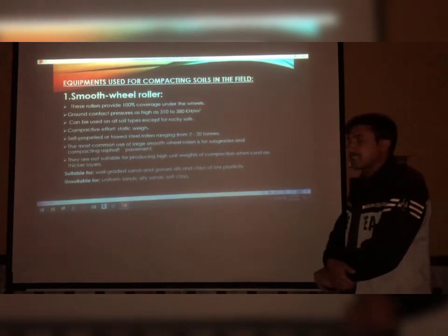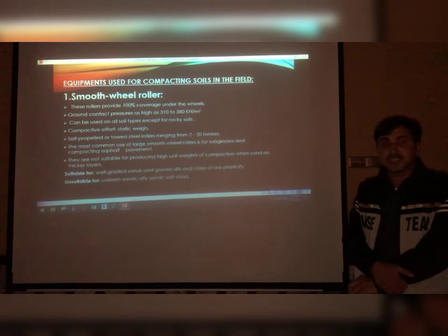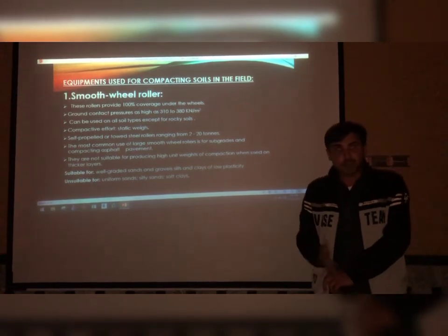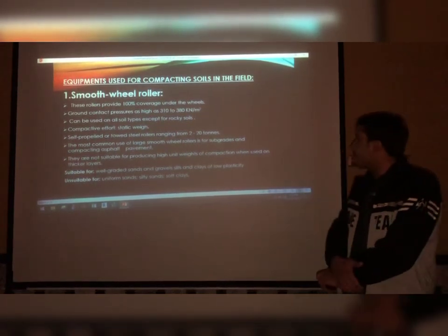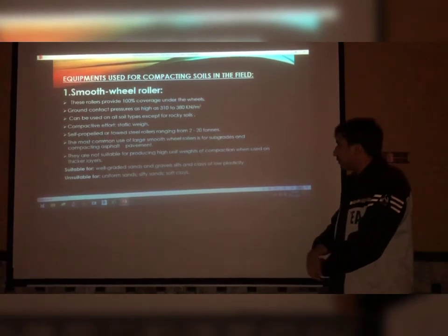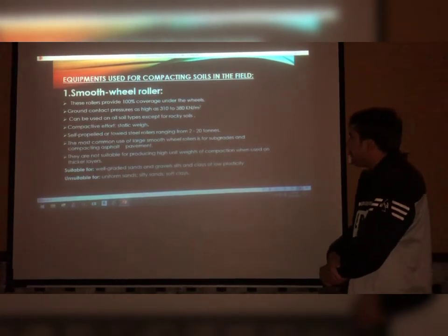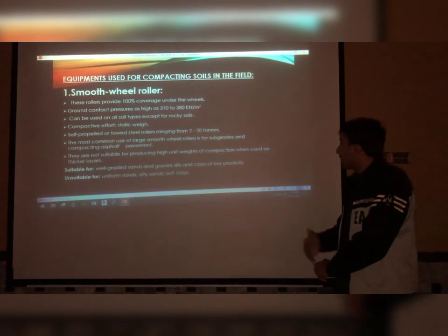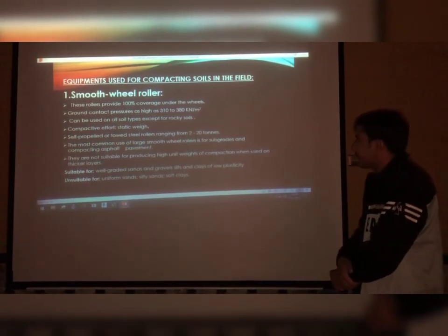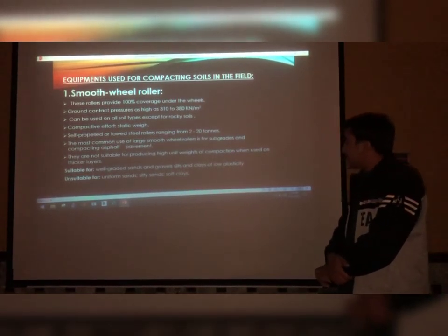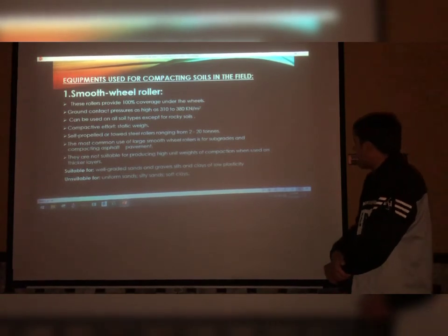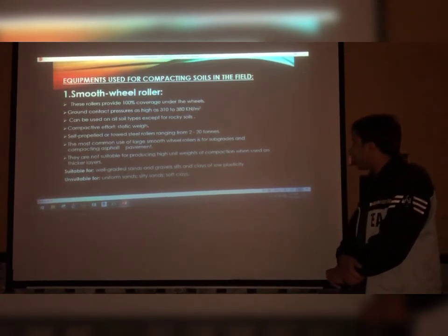Compactive effect is static weight. Static weight means they do not vibrate, and do not move up, down, left or right. They can compact with the help of their own weight. They are self-propelled or tandem steel rollers ranging from 2 to 20 tons. The most common uses of large smooth wheel rollers are for subgrade and compacting asphalt pavements.